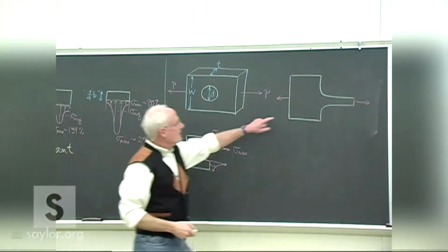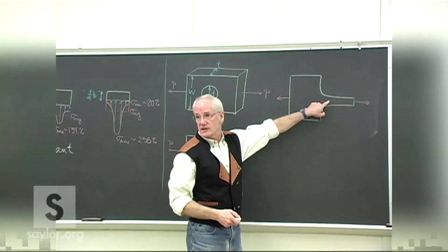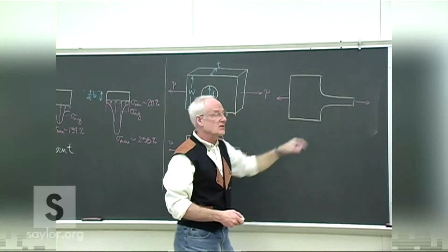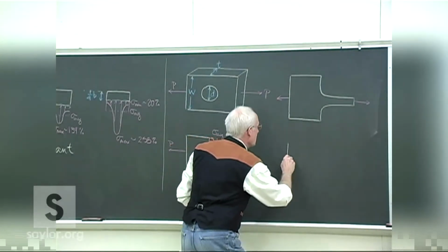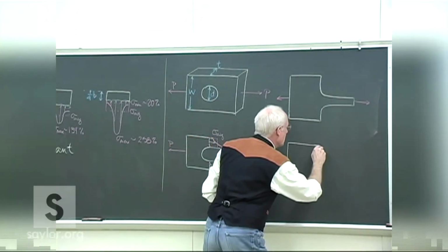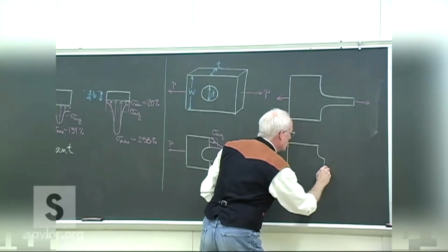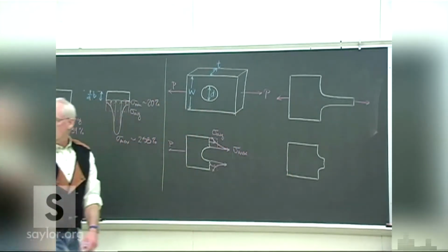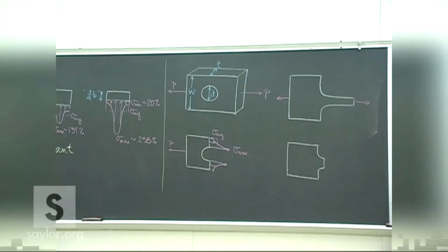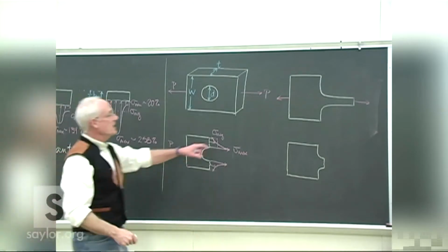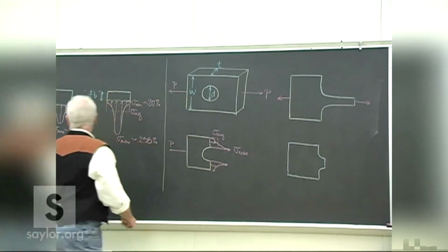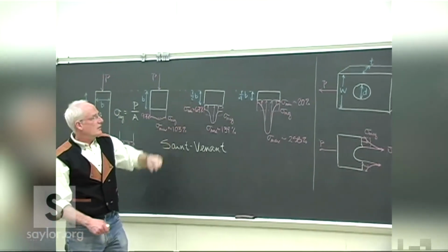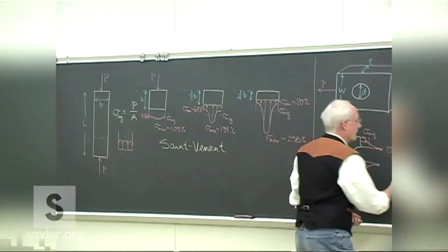we find that very, very close to this contraction in area, of course, when we go to a much smaller area, the stress goes way up, but not only does the stress go way up, but the maximum stress goes way up. Not only have we brought down the area, but we've gone to a change in geometry that has caused this non-uniform distribution to reoccur.